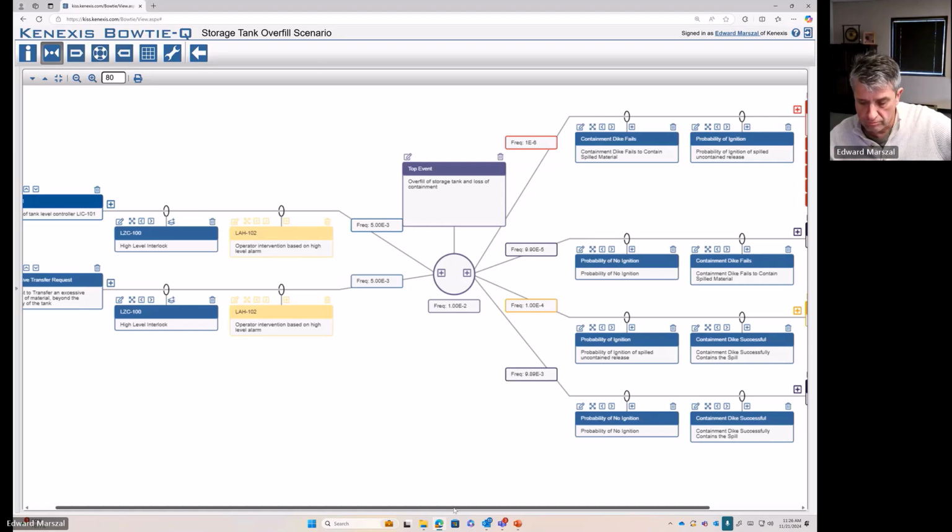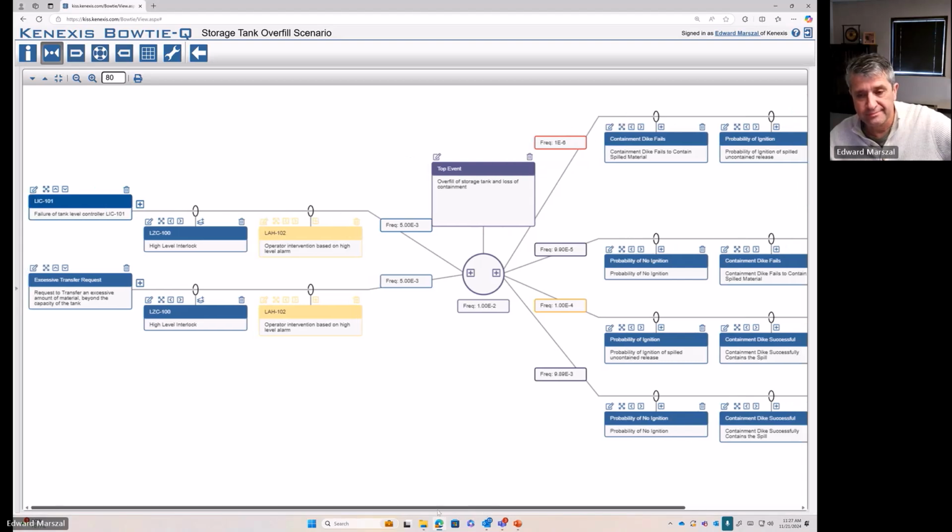And in that case, maybe this question makes some sense, regarding that the PFD is going to depend on the number of causes that it's covering. But that is done in a LOPA study when you aggregate all the risk reduction factors. But here, the PFD of a high level alarm, for instance, is 0.1. There's no question about it. That was more or less what I was trying to do. That's the motive behind my question.